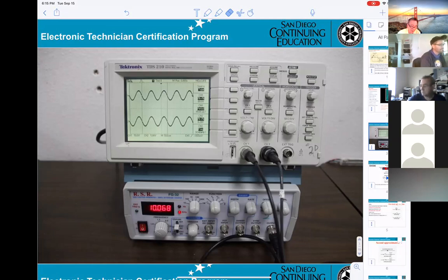However, you must understand the company is not like the school. The company uses their own oscilloscope. That means you only measure the time. You cannot measure the frequency. You want frequency, you have to use F equals 1 over T to do your calculation. The reason is the company doesn't want to change the scope. They are still doing a good job.